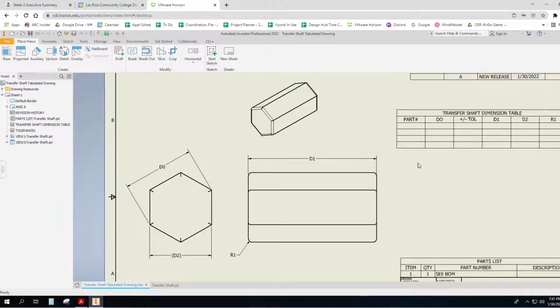So if there's a 3D printed part, it comes out 0.016 inches too big. So let's say I wanted this to be 0.541. If I 3D printed it from a model that was built 0.541, it would be bigger than that by 0.016. And that could cause me a problem. So I would have to actually shrink this dimension by 0.016 to make a 3D printed version of a set of parts. And I want to know that.